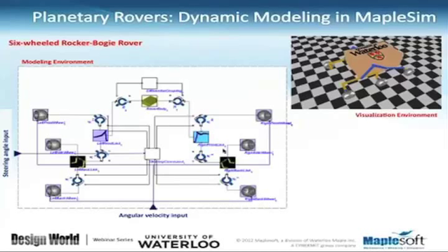Now, in order to add the other components, like the control of the steering system or the drive of this rover, then we have connected this revolute joint, which is in the front one, and this revolute joint, which is the one in the back.